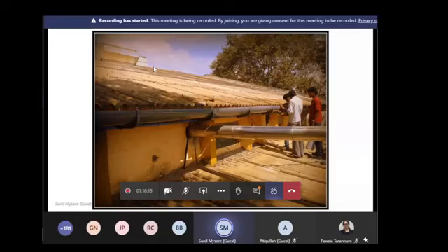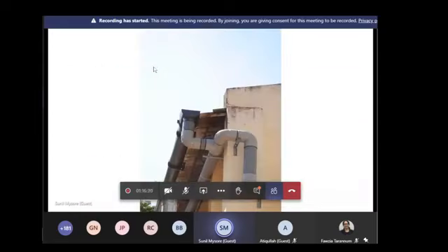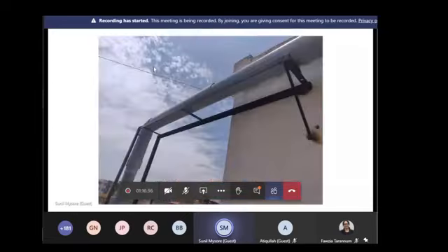There is a question on asbestos sheet. You can see it's being done. This is a typical arrangement in a residential apartment. This is how this net worked. This is gutter coming into a pipe, and further it's going somewhere else, so the gutter and pipe together. Here you can see there is no support, so we have made an MS connection so that the pipes are supported properly.